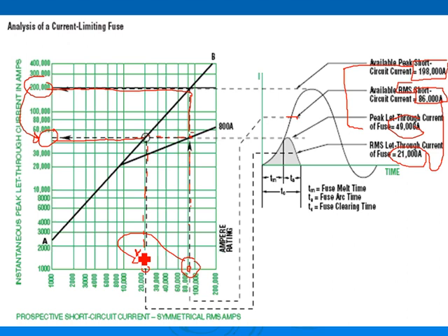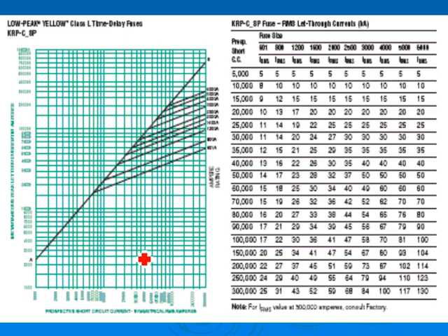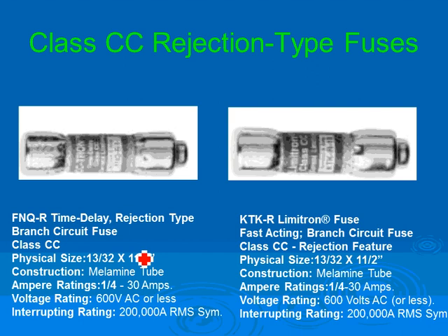Any comments? You know what they do on the utility side? On the utility side, they use fuses that, when the current goes right through them, turn into insulation if it's too high. It chokes the current. On the low voltage side, what we do is open the circuit breaker fast enough, or use the fuse circuit breaker. Here's a table, guys, from manufacturers that gets you multiple current limit fuses that you can size for different services.